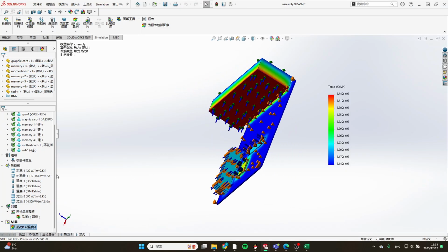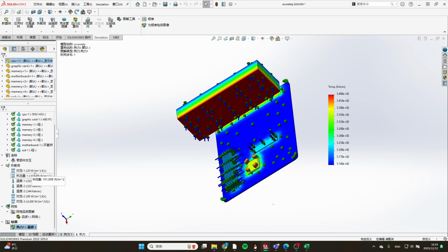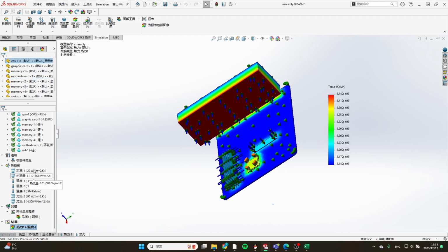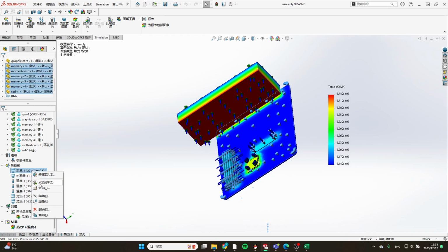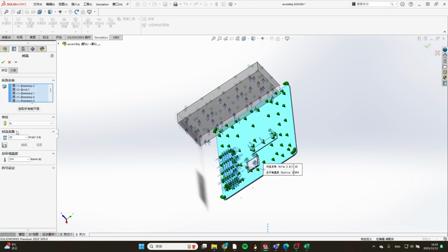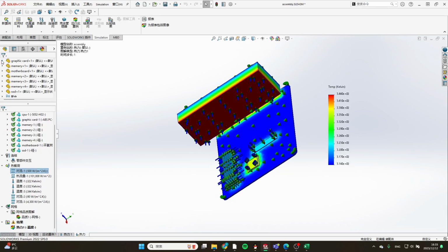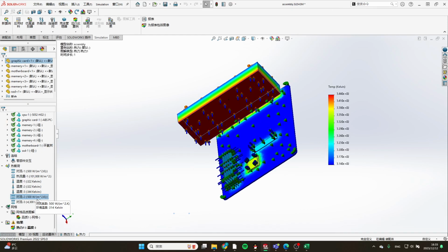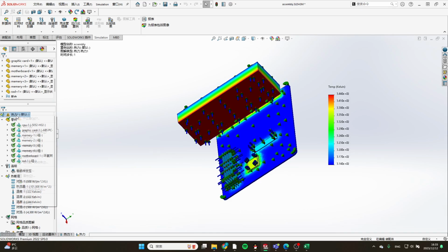So right here, this value has already been set from common settings at 20 watts per meter square Kelvin for motherboard, 90 for a stronger one, so it's 90 for GPU. I'm going to change it to an extremely high value, like 500 for both, and hold the value for CPU constant and see the result.